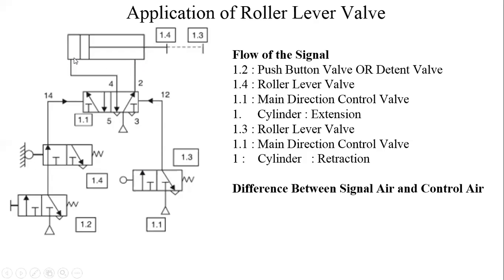So when to start the extension stroke will be based on activation of roller lever valve 1.4. When to start the return stroke will be depending on activation of roller lever valve 1.3. Now please note this important point here in your notebooks.